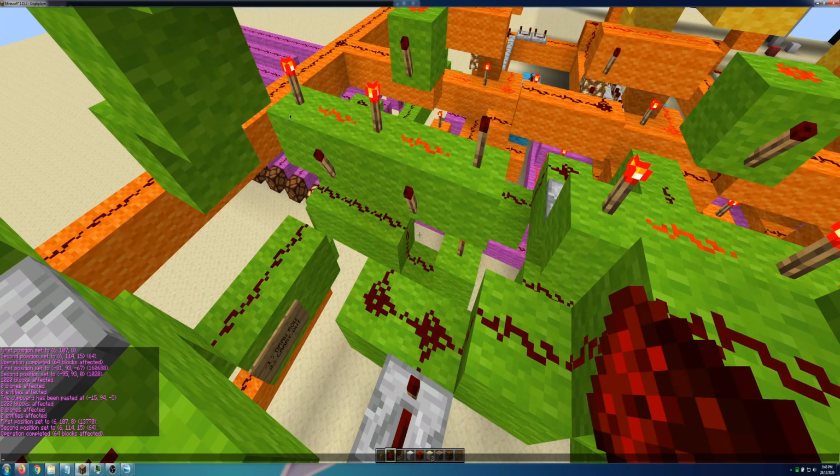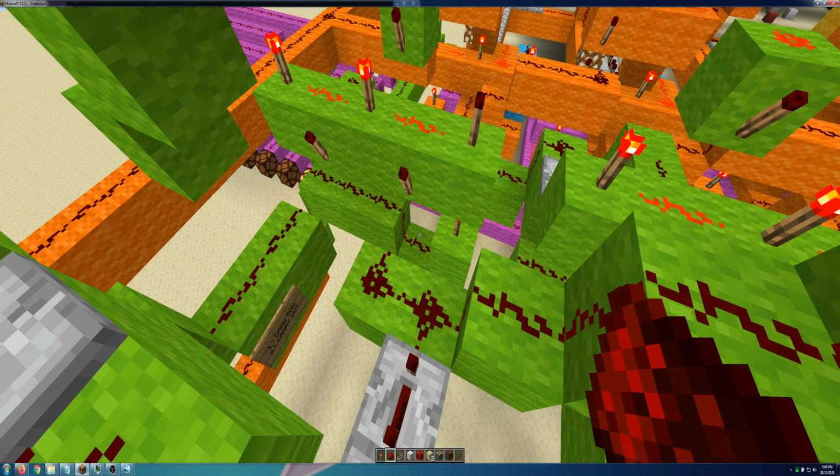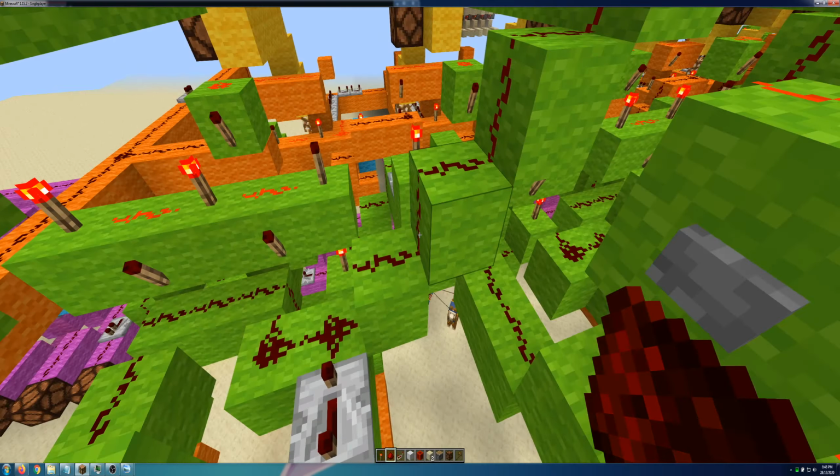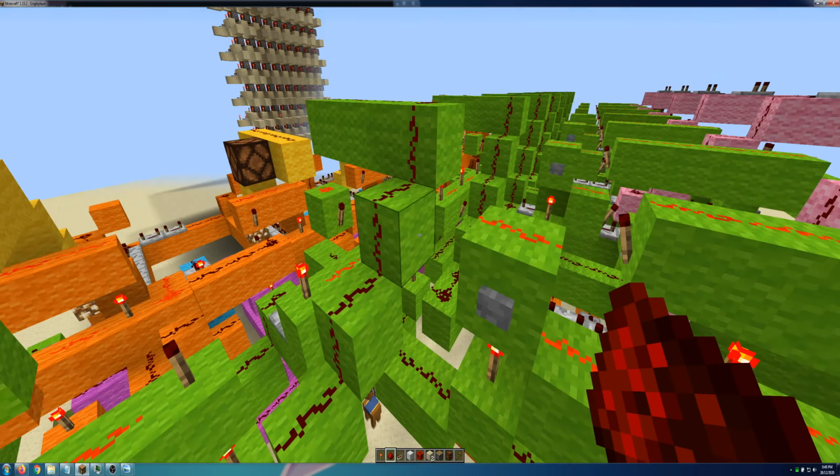Here is the input for if the row should turn on or not. If it's turned off, then this directly inverts the signal on the other side of the AND gate. And so when it initially gets that start signal, if it doesn't want to draw this row, then instead of going through all that repeater, latch, all that drawing the row, it would just simply output an on signal to the exact same place after the repeater stack. So then it will carry on to the next row.